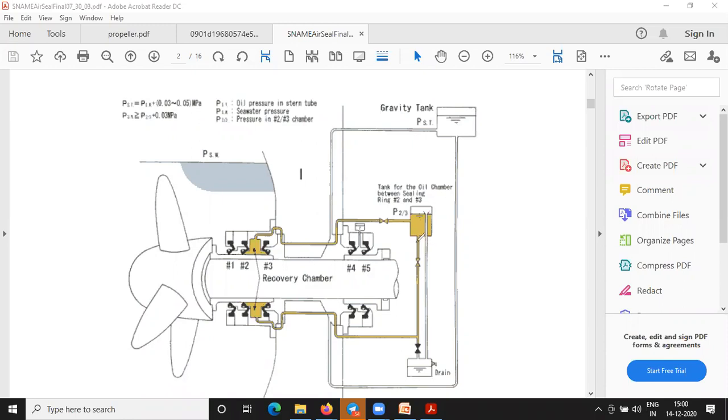So again, the different systems have got different technologies. Like you have seen in the turbocharger, there was a sump, and the sump is taken for the lubrication of the bearings here. This sump needs to be cooled. Why? Because the oil quantity is very less here. So for that cooling, we have the water casing for the turbocharger.